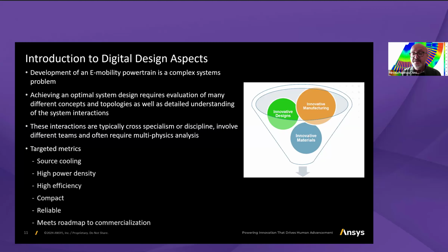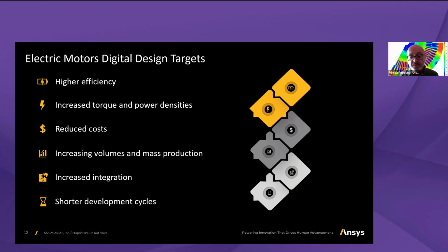And last but not least, innovative materials. What materials can be brought into the question? So then we improve the performance, either electrical steel, winding materials, materials for the cooling system. Obviously, as well, the PM machines, permanent magnet materials, can be considered: what materials are innovative and can be used with lower cost.